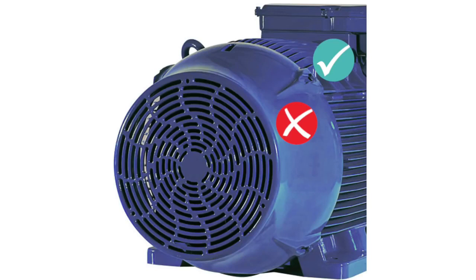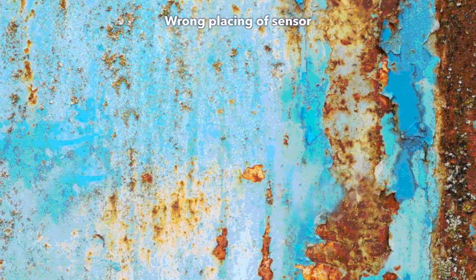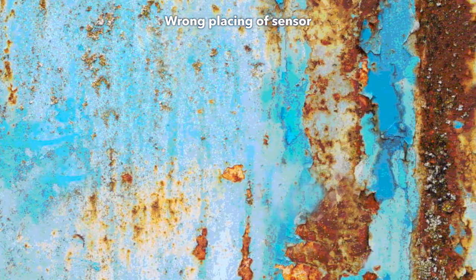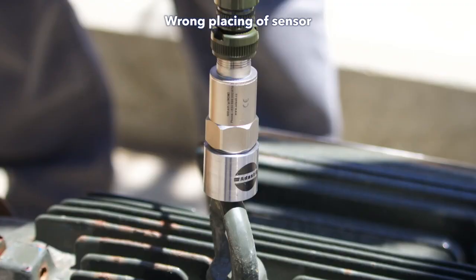Do not measure on motor fan covers. Fan covers are weak and they don't transmit the real vibrations of the machine. Bearing vibrations are not there at all. Do not measure on rusty or painted, or both, bearing housings. Rust and paint significantly dampen high-frequency vibration transmission.